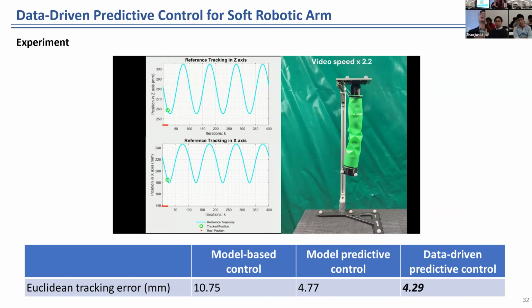And going back to your question about the degrees of freedom we may need, we have 3 degrees of freedom for XYZ, and then we have rotation. The idea is that this rotation can help detach the fruit. But after we talked to the growers, they actually had mixed feedback about this rotation part. For some varieties, they said it's better to just pull so that it could better retain the stems and cause less damage to the tree. But for some varieties, it's good to twist. So I think we need to have that functionality, and later we can try different picking patterns. For example, you can go back a little bit, then twist, and then pull. Maybe it's better. So there are more explorations to do, but we have those 4 degrees of freedom.